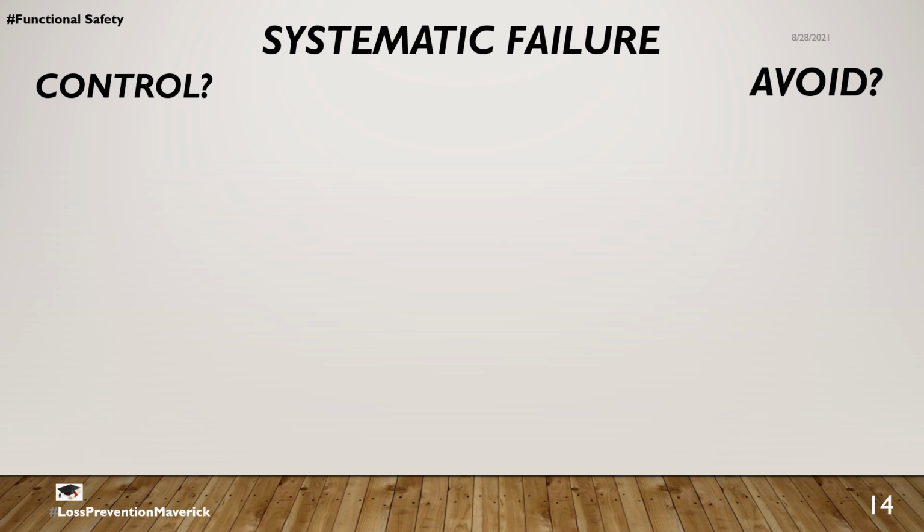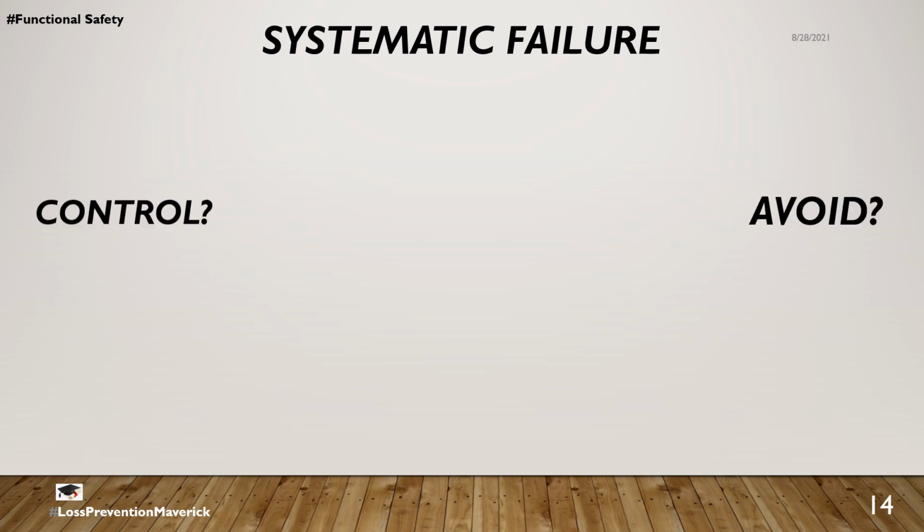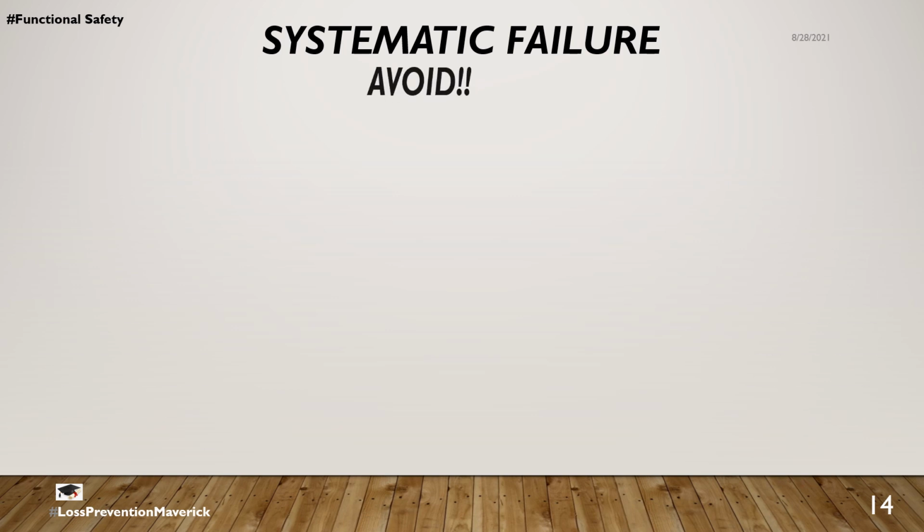This is something that happens because of lack of functional safety management. That is, possibly the hazard was not identified properly, and because of this the safety function was not addressed, or maybe the safety function was addressed but the system integrator's language or code was wrong, or maybe all that was right but because of some assembly process something went bad, or maybe the operating procedure was not apt for it, and therefore these kinds of systematic failures can actually be avoided.